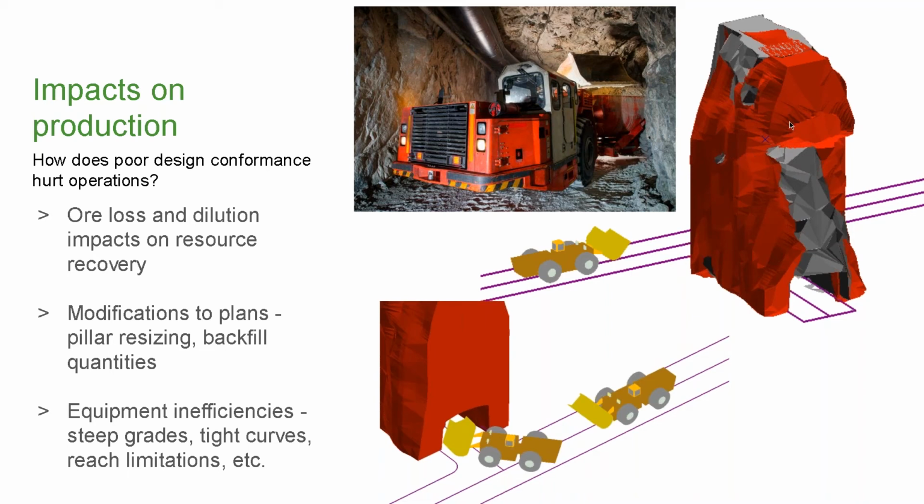Other issues with overbreak is with a primary and secondary stope configuration. If we overbreak both of the primary stopes, we might have to modify our plan, resizing pillars or redesigning our secondary stopes to ensure proper stability in the area. With backfill, with overbreak being considerable, depending on our backfill type, either being cemented or paste type backfill, there can also be costs associated with these larger voids.